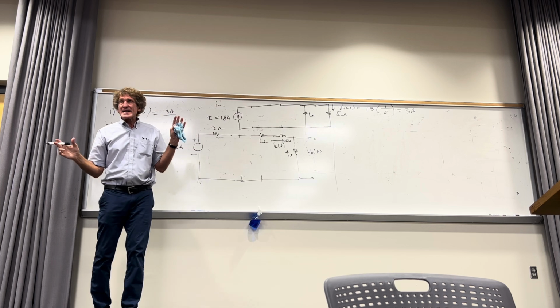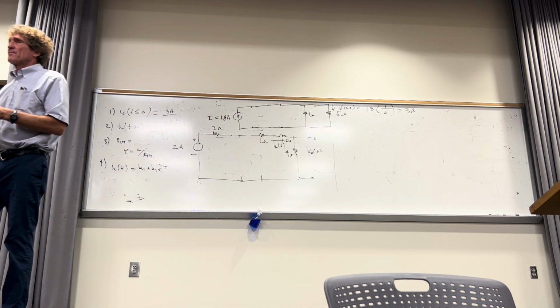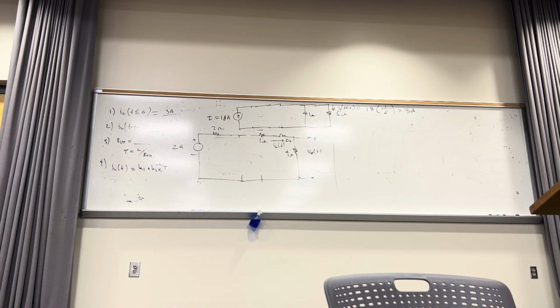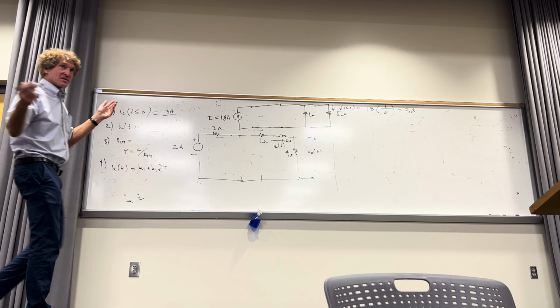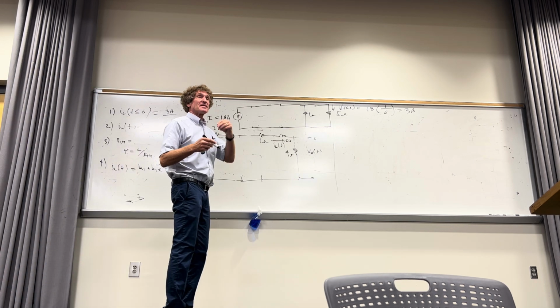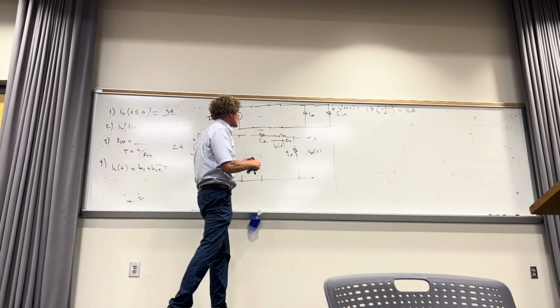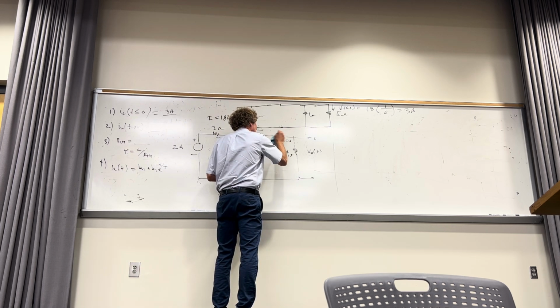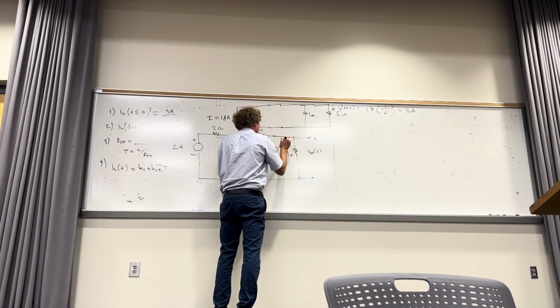Yeah. All right, now we're going to go for the current as t equal to infinity. What does the inductor look like as t goes to infinity if there's nothing time varying? Class? I can't hear you. What is it? It's replace it with a short circuit. You all with me? I mean, there's no wrong answer here. If you want to say a wire, it's fine. Whatever, something that really lets me know you might as well just put a wire across it. So it looks like this. Right?